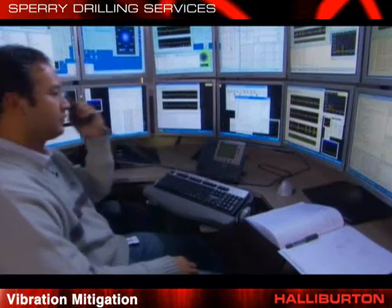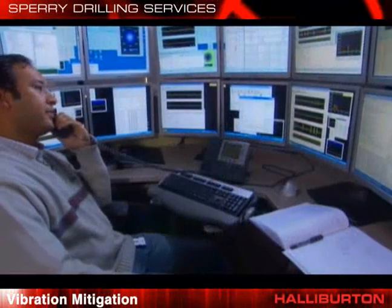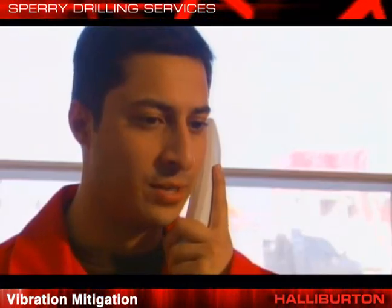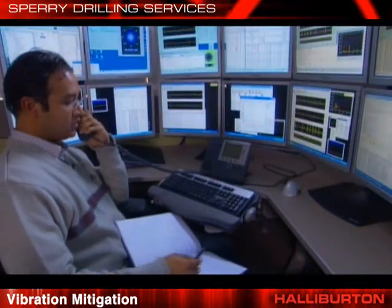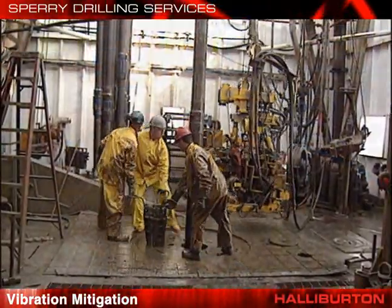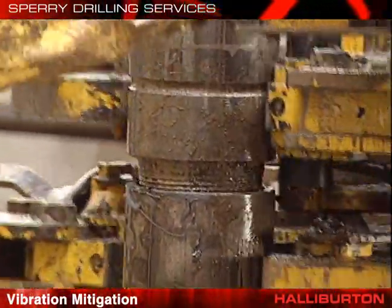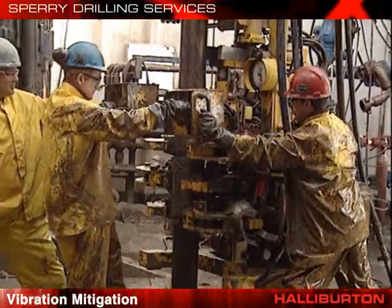Of course, measuring and responding to the complex array of vibrations while drilling is a real challenge. That's why Sperry provides specialists from the Applied Drilling Technology Service, or ADT, to help you determine the vibration mode and mechanism that's causing your problems, and come up with ways to mitigate it. The ADT Optimization Service will also identify ways of preventing the vibration from occurring on subsequent bit runs or wells. By modeling the expected conditions and making the correct measurements while drilling, we can virtually eliminate vibration.